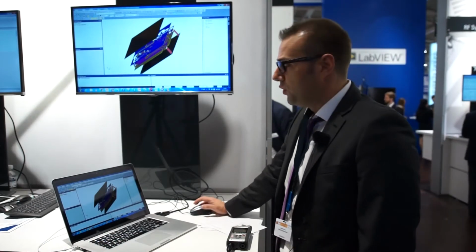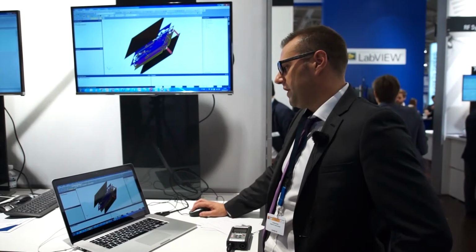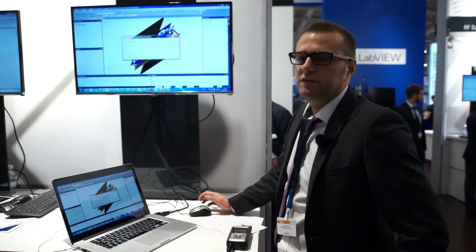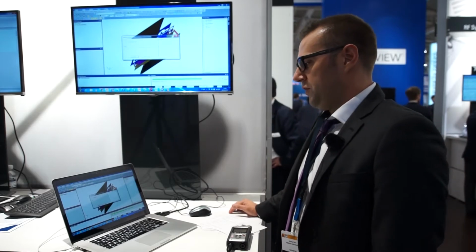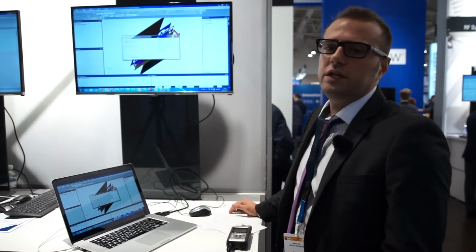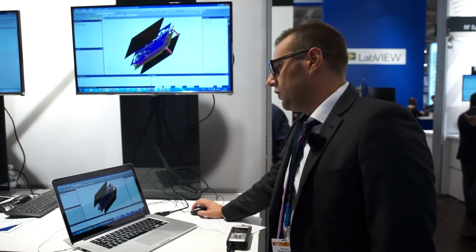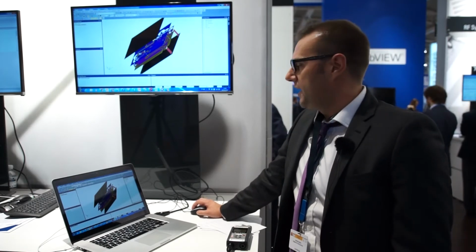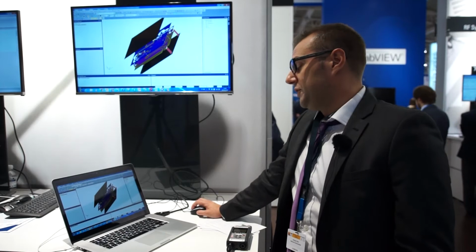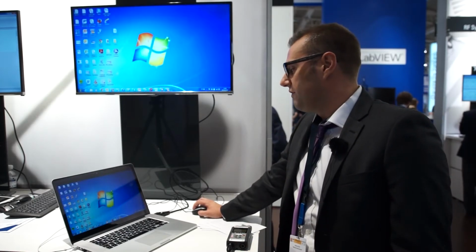This is not just geometry, it's actually a project ready to be simulated. So I just use the validation check provided by Ansys HFSS, and you can see that this is a project that I can directly simulate without the need of doing any additional functions. What happens now, I cannot do the simulation in real time of this complex project, but once I run the simulation, I can bring back the results. The S parameters are automatically brought back into the AWR design environment.